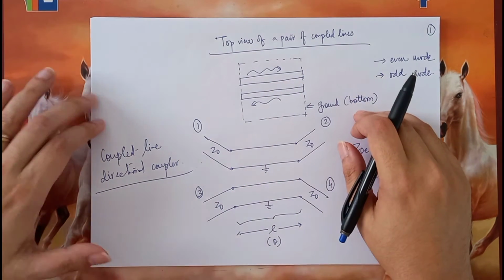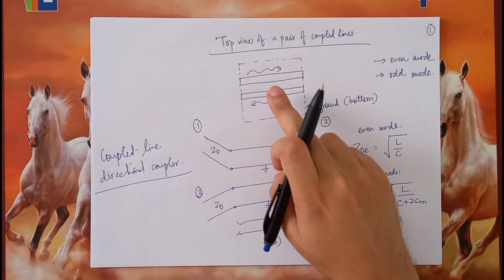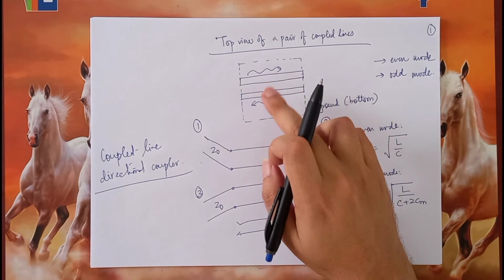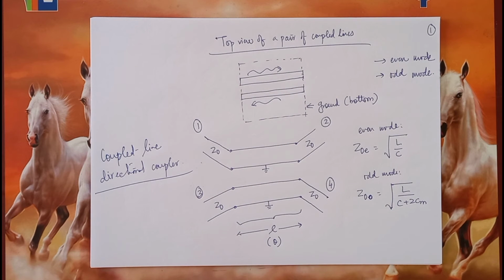As we discussed, one possible application of these is in probing transmission lines, where physical connection of voltage probes or equipment to the line is not possible due to loading and power division. Just by sampling a small portion of the power from the main line, we can back calculate the power or the wave magnitude in the main line, and that is very, very useful in measurements. Right?